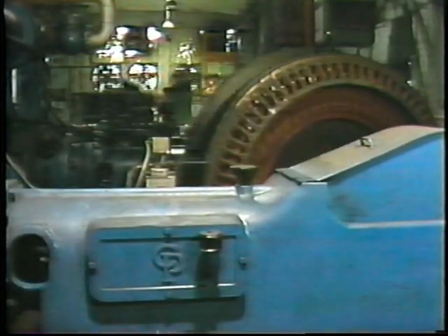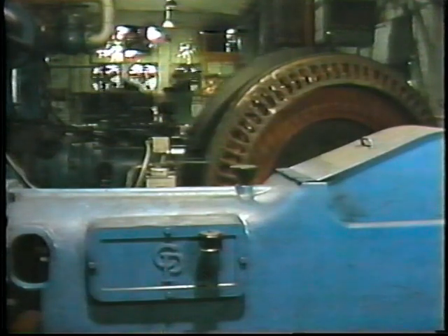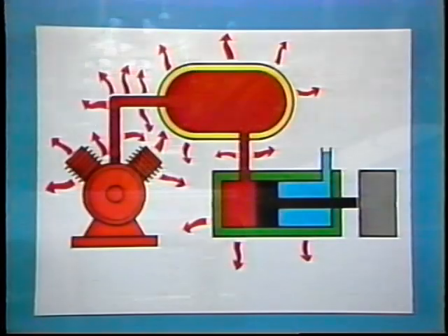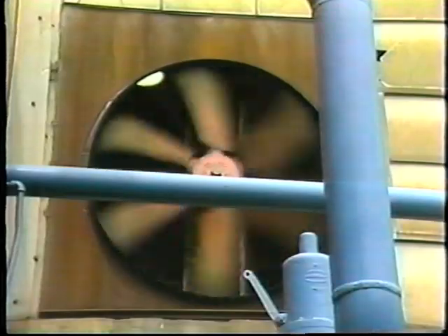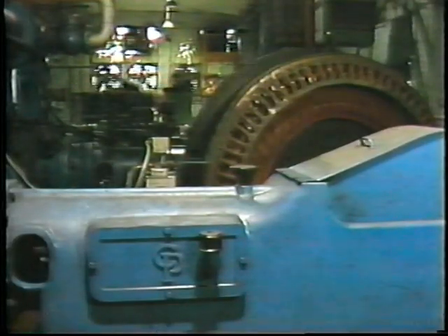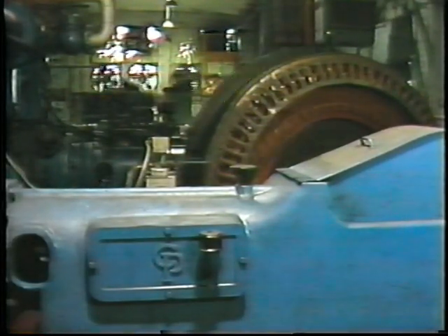In the process of compressing air, approximately 50% of the input power ends up as heat. This heat must be disposed of in some way. Part goes into the cooling water if water is used, but the rest goes into the surrounding air. Therefore, exhaust fans are usually an essential part of the system, particularly if the compressors are in an enclosed area.